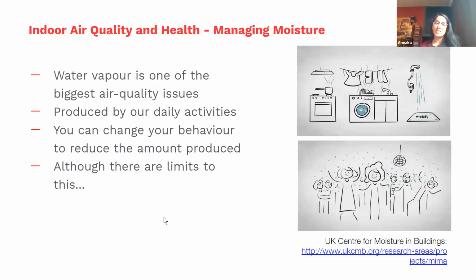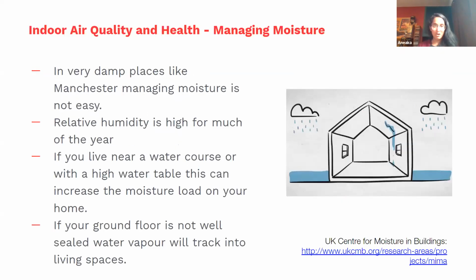There are various things that impact indoor air quality. So I'm going to spend a chunk of time now talking about moisture, because it's one of the most significant ones. It's produced a lot by lots of our daily activities. Just existing in your home, you breathe out water vapor. I don't know how many people watch the videos, but it's got a really nice illustration of this. And plants will breathe, animals, drying our clothes indoors, having showers. And obviously we can change our behaviour, but we can't stop existing. So we're always going to have moisture being created in our homes.